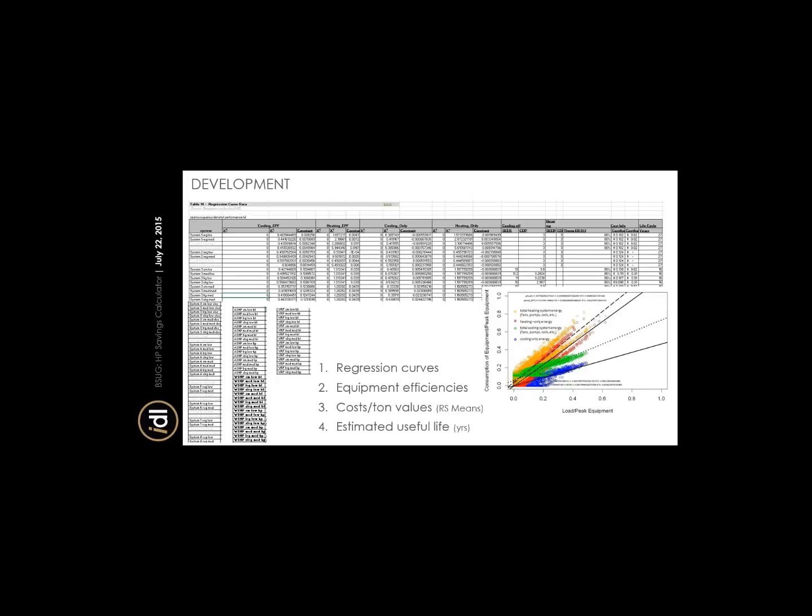You can see we started off pulling out just cooling and heating energy use from those curves, and then we realized we wanted to take the miscellaneous cooling and heating loads, which are basically equipment, pumps, and fans, and we wanted that separate, so we ended up going back and pulling out those loads as well. So in the end, we could get the results for end uses of all of them separately, cooling, heating, and equipment.